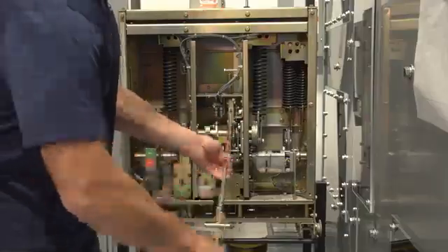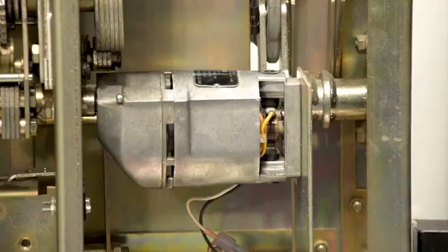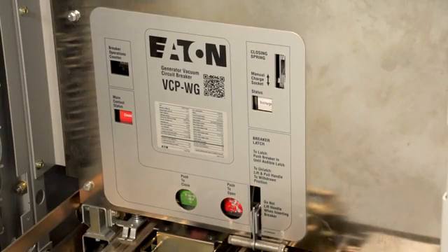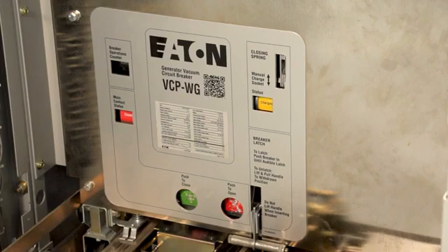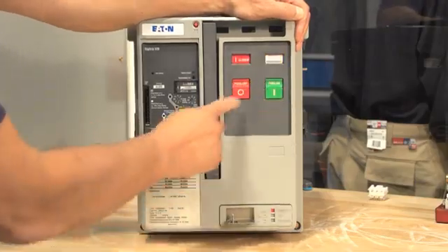For low voltage and medium voltage power circuit breakers, in order to close these breakers, springs must be mechanically charged either manually or electrically via this motor that looks like a drill motor. Note that the opening springs charge with the motion of closing the breaker so that it's always ready to trip. For example, if it's closed into a fault condition, you can always open the breaker, but you have to charge the breaker to close it.